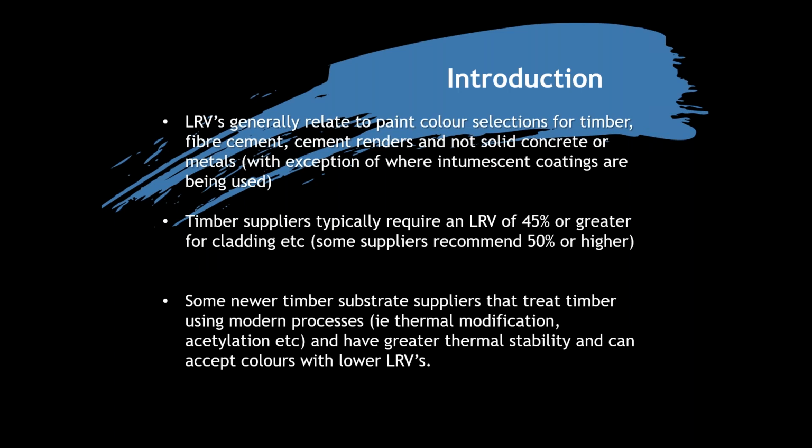So where do they sit? So LRVs generally relate to paint color selections for substrates that are affected by heat stress. So you're talking your timbers, fiber cement, cladding, your cement renders. They generally don't relate to solid concrete and metals or substrates that aren't affected by heat stress.